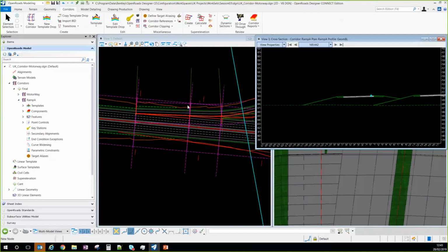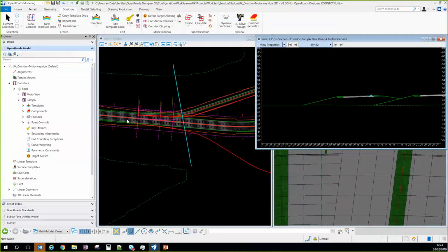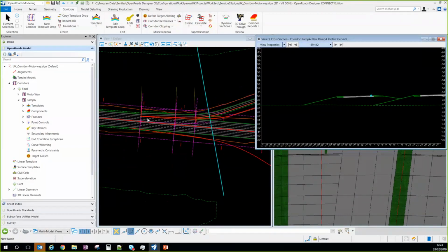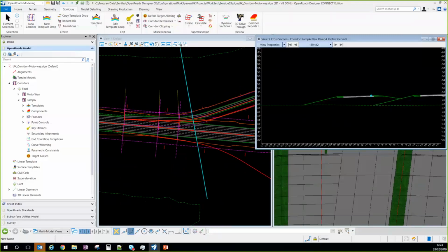More or less it was what I wanted to show you for the slip road design, so for the nose, for the verge behind, and now I wanted to show you also the curve widening. I will show you how to use the curve widening command, which is also here, create curve widening. It's used to automatically create and apply horizontal controls to widen a lane around curves.